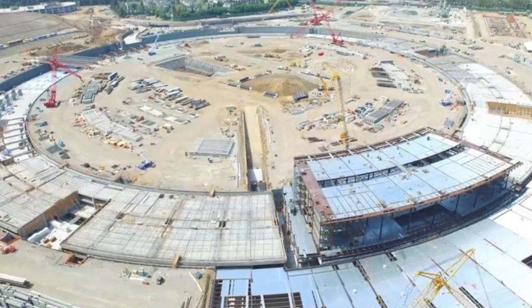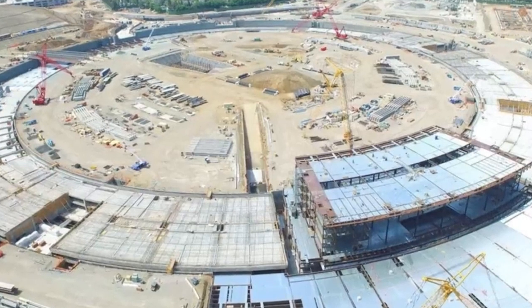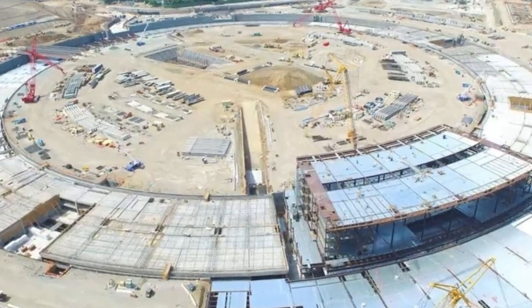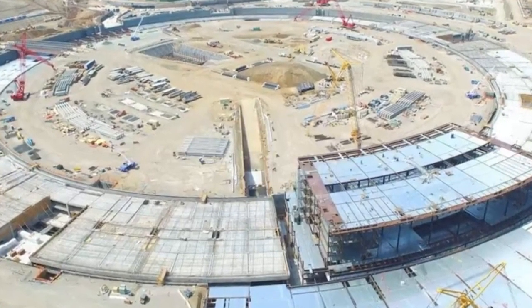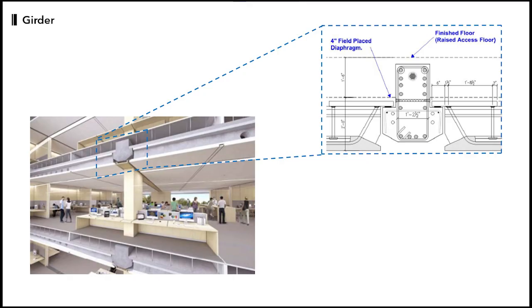The void slabs rest on ledges of precast post-tension girders or on a continuous ledge at the shear wall lines. The support connection chosen was a truss hanger bar, a rectangular steel bar with welded inclined rebars that transfer the reaction into the stems of the units.